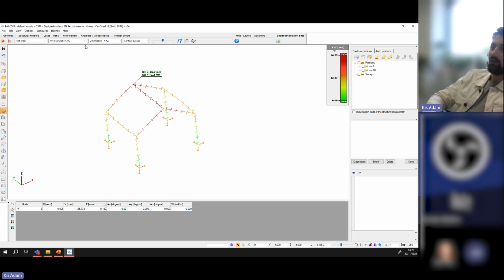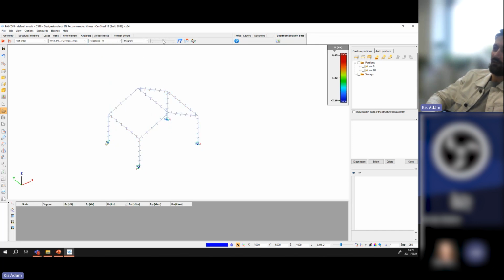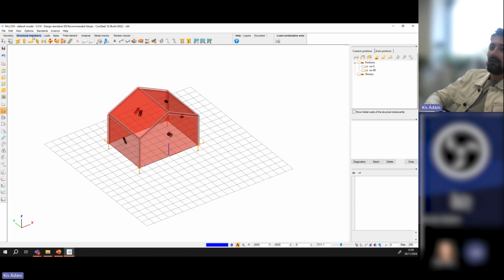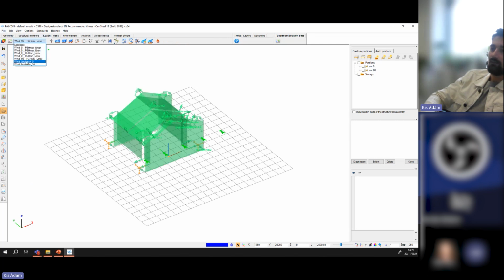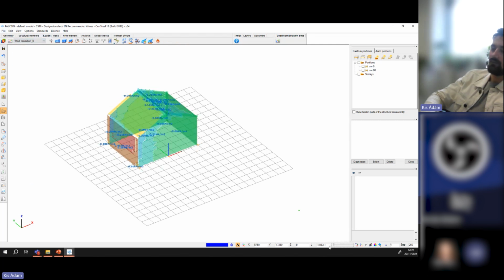Let's compare with the Eurocode. The Eurocode is a bit higher, like 20 or 25% at max. So I have values that I can compare. Again, we have reactions that we can check, or we should check maybe, because we can have a global reaction or the reactions of the structure. So again, these are loads that can be applied to the structure directly, and I can regenerate and reevaluate it really easily. The simulations can be re-performed.